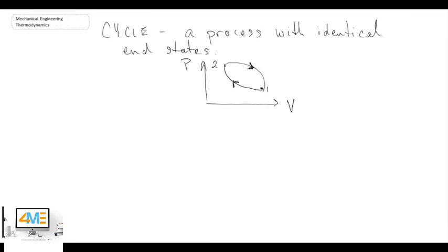And the last thing that I want to mention is the fact that within thermodynamics, remember we talked about equilibrium and saying that systems needed to be at equilibrium or within equilibrium in order to define the properties. Well, in reality, systems that we study are not in equilibrium, but what we do is we make a bit of an approximation through our modeling, and that is that we study what are referred to as being quasi-equilibrium processes. So let's define those. Quasi-equilibrium processes.